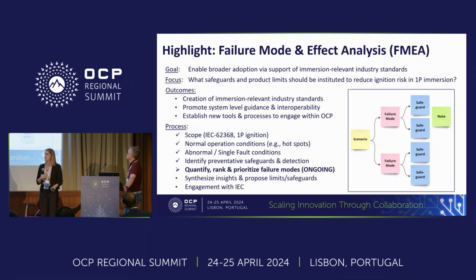The second piece of work that I want to highlight is called FMEA, or Failure Mode and Effect Analysis. This is a very, very important work stream within our group. The reason it's so important is that the end goal is for us to use the insights and content generated by this work in the community to actually advise industry standards and codes bodies. This is one of the biggest hurdles right now to bringing an immersion system into your facility: understanding how it impacts things like building codes, storage limits, PPE required, and special clearances that you might have to get,